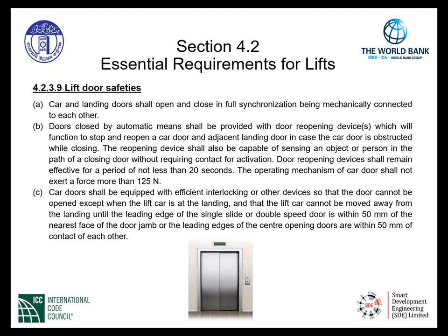Finally, item C, car doors shall be equipped with efficient interlocking or other devices so that the door cannot be opened except when the lift car is at the landing, and that the lift car cannot be moved away from the landing until the leading edge of the single slide or double speed door is within 50 millimeters of the nearest face of the door jamb, or the leading edges of the center opening doors are within 50 millimeters of contact of each other. These three important key areas make certain that the installer and manufacturer must provide these safeties regarding lift door and lift door assemblies.